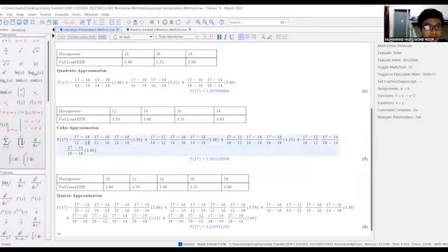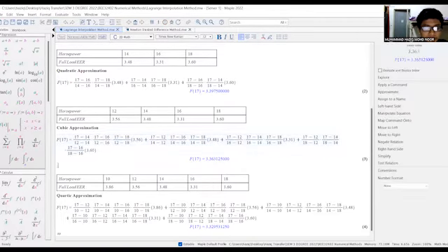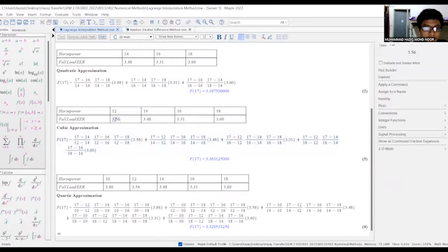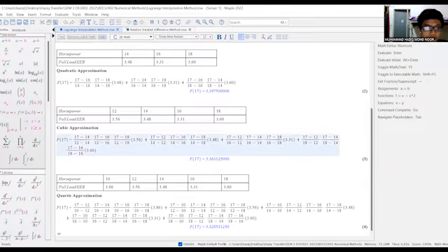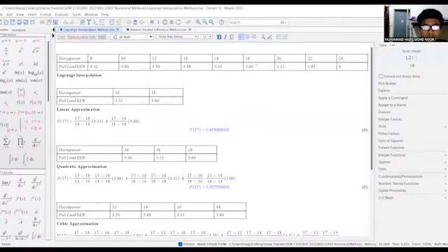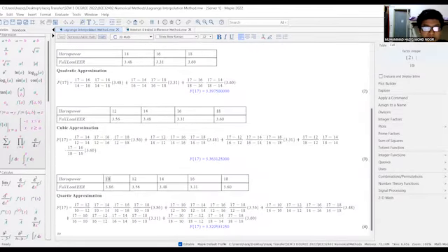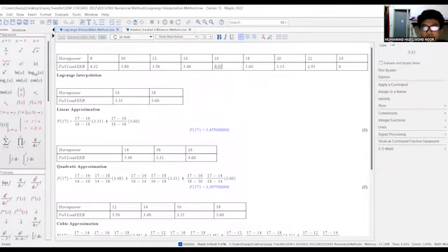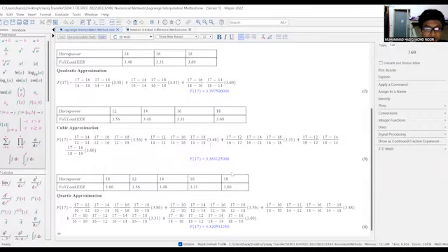And we go to the cubic approximation, which is quite longer. You will see the same formula, and when we calculate the formula for the A, B, C, D parameters and X, Y, you will get 3.363. For 17 horsepower, between 16 and 18, we get 3.363, which is also logical, and it is between 3.31 and 3.60.